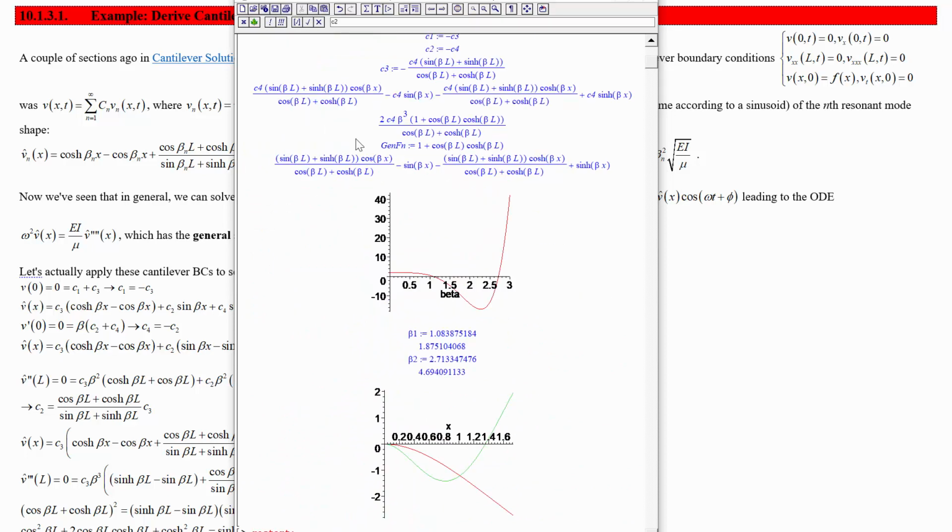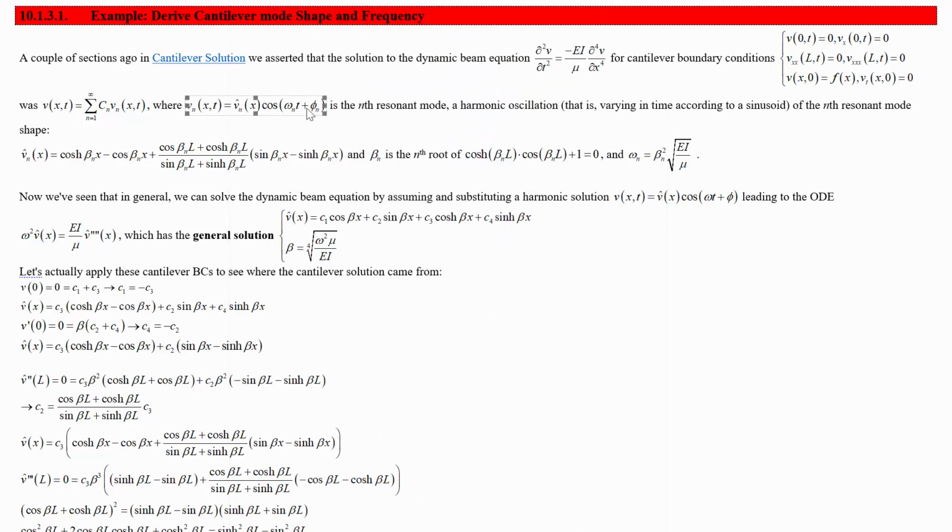Well, that's the same mode shapes as we had before. Looks like they're flipped. Again, doesn't matter. They're the same mode shape because what you're going to be doing with them is multiplying them by that harmonic term. So even after you multiply them by that harmonic term to get the modes, you're going to be taking a linear combination of all of that to find the actual solution.